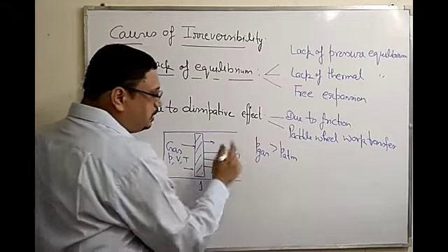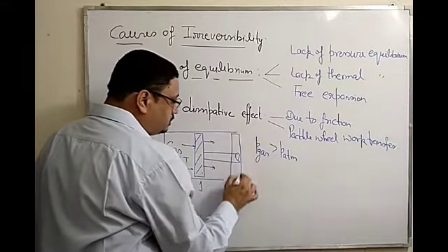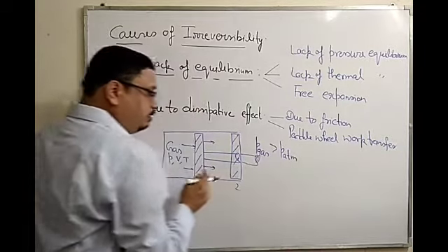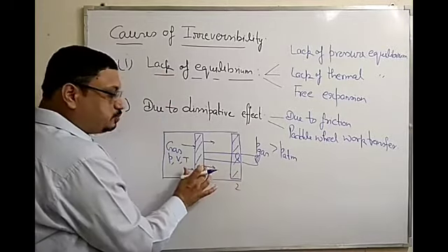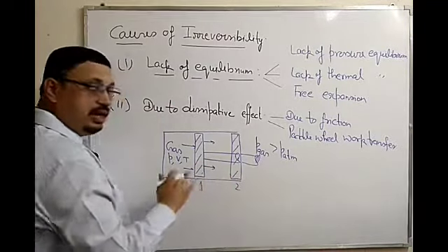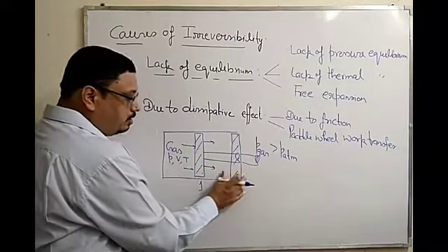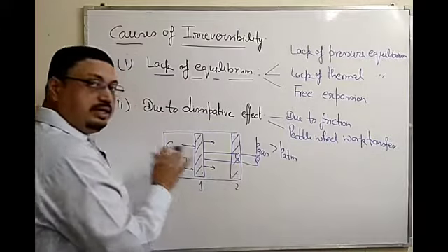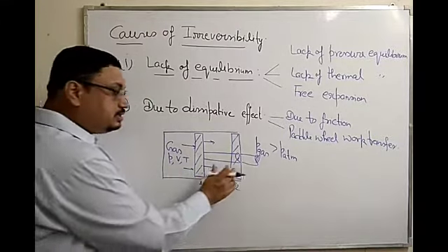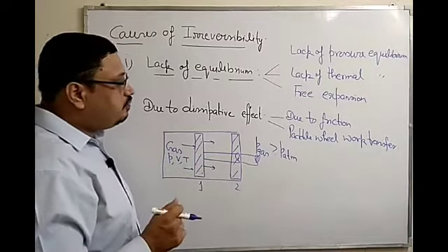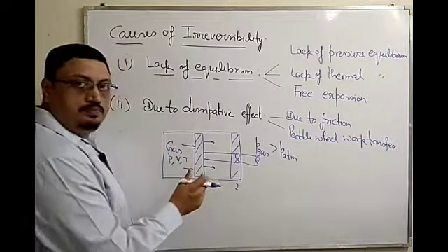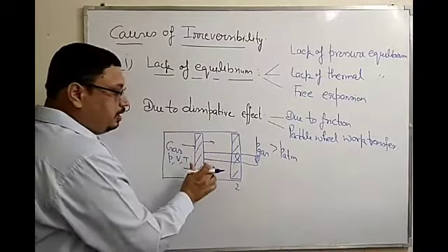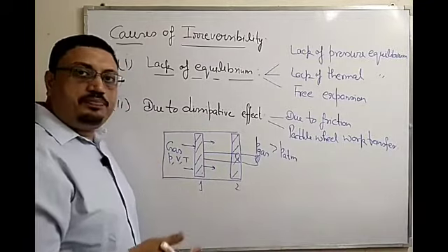And if this piston is displaced to a new position, state 2, then this process is not a reversible process. It is an irreversible process, because we cannot bring back this piston to this position without any external effort, right? This is a practical process and an irreversible process. Now we must see the reason that this process is irreversible. The reason is the pressure gradient, the difference in pressure. The more the pressure difference, the more the irreversibility.